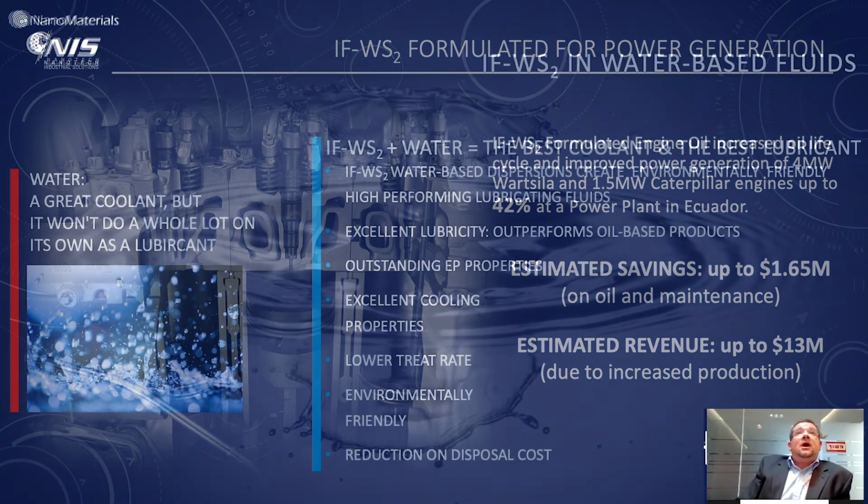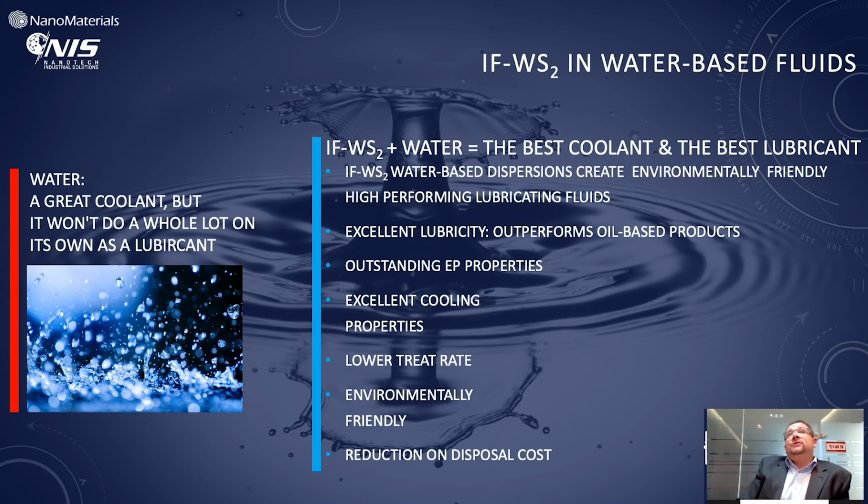One of the recent developments that I want to mention today is water-based products, which are not typical for industry and can be used for metalworking. Metalworking requires good cooling, but also requires lubrication. Up to now, some combinations of emulsions of oils in water were used, but it raises some questions from an environmental point of view. Water itself is a great coolant, but it's not a lubricant at all.